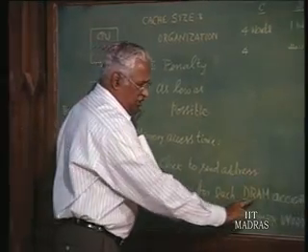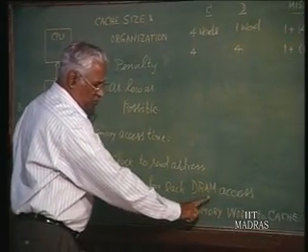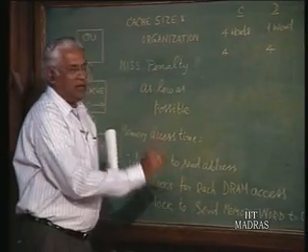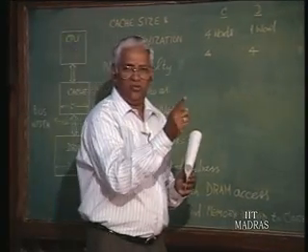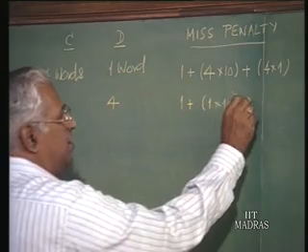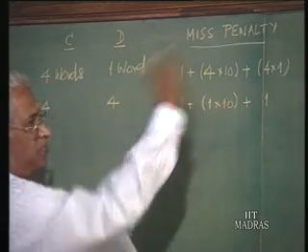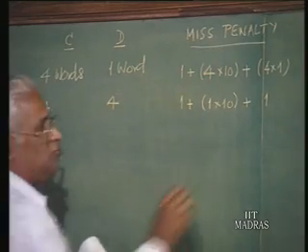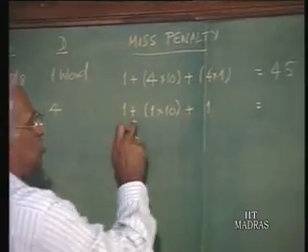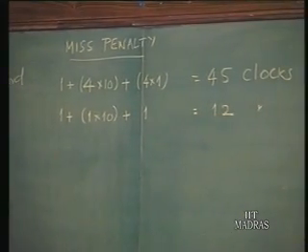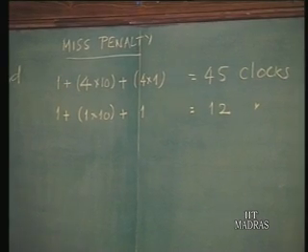It says each DRAM access. Now, in this case one DRAM access is going to access 4 words. So, only once a reading is to be done, 4 words will be got, and just in one step the 4 words will go into the block. So, now we have only 12 clocks, right, 12 clocks, good.